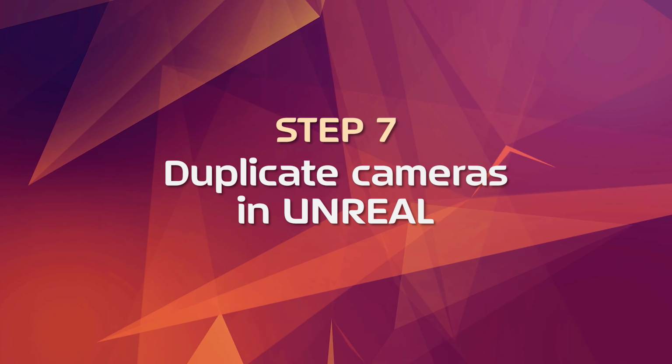Once again, Unreal will have offset the new camera's location, so in the Details panel, click to reset its location. Okay, click to make sure UECam03 is selected in the outliner. Press Ctrl D to duplicate it. Press F2 and adjust the naming to be UEUbercam01. And again, Unreal will have offset the new camera's location, so in the Details panel, click to reset it.